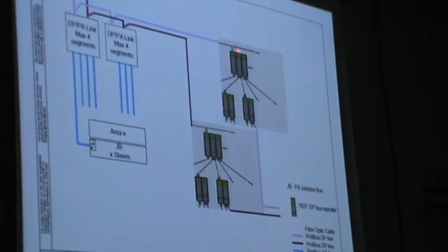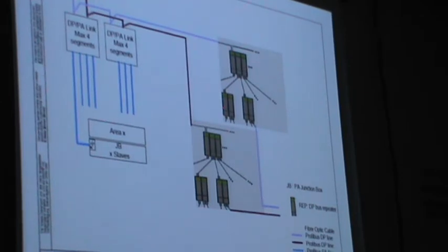So like this is the DCS. The first cable will be communicated with this repeater, and it will be distributed to the field. In the field you also have the repeaters in the JB. For example, in our RO area we have more than 5 or 7 motorized valves in 1 JB.